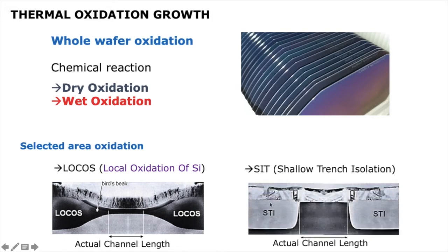Similarly, you have shallow trench isolation, right? You see the shape of this oxide layer here, it is a much sharper and thick oxide layer. So these are also separators. You essentially have the device at this point, and this is again a separator.